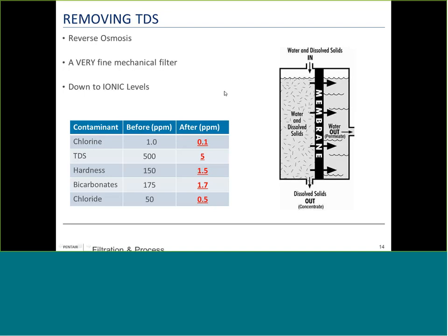So as we go down this membrane and we reject more and more of the TDS, this becomes more and more concentrated in TDS as we go down the membrane. And then the water that comes through is going to have 90 to 95% less mineral content than this side, where it's sent out to a storage tank, such as a bladder tank, RO-Mate 40 or such here.